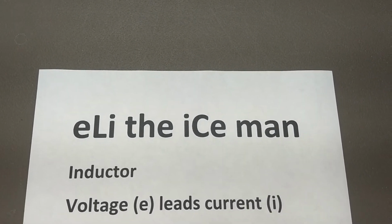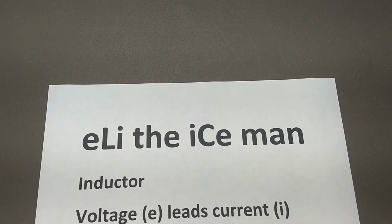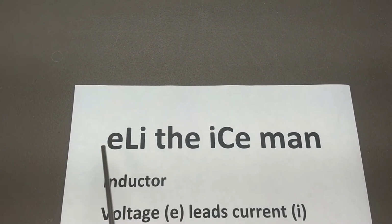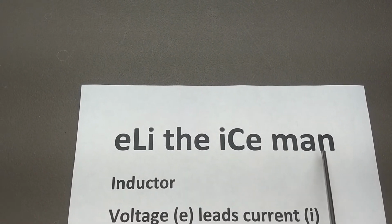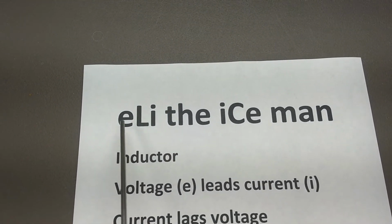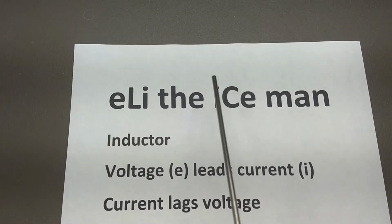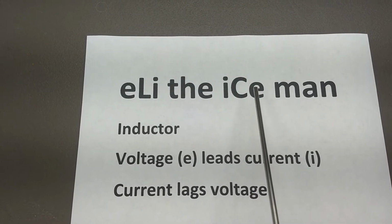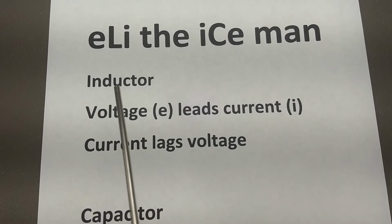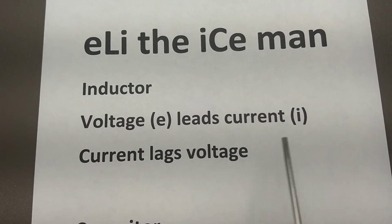And there's a saying here that can help you remember the relationship between the voltage and current. And that little helper is Eli the Iceman. And this will help you remember that in an inductor, E leads I. And in a capacitor, I leads E. So here is the statement in words: voltage leads current.